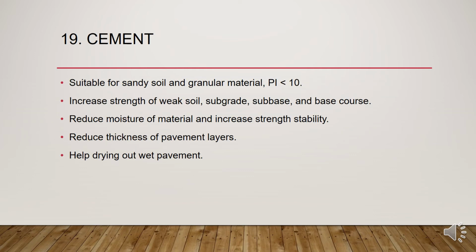Cement stabilization. The second most suitable stabilization binder which has been selected for Afghanistan is cement. Cement is suitable for stabilizing sand material with the PI lower than 10 and granular material. Cement stabilization increases the strength of weak soil, subgrade, subbase, and base course material also.